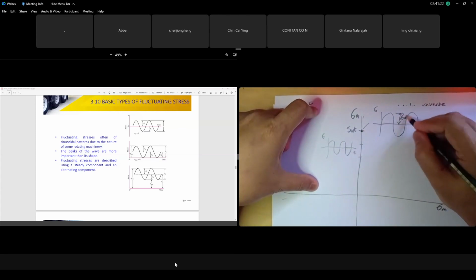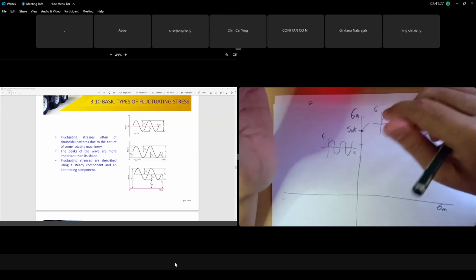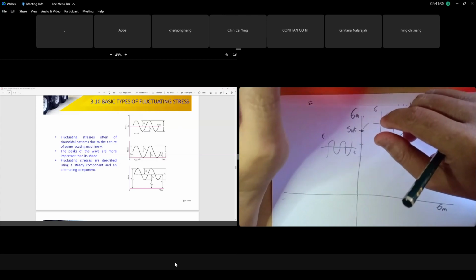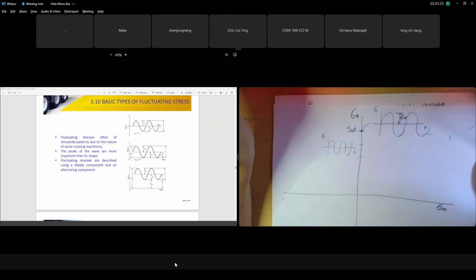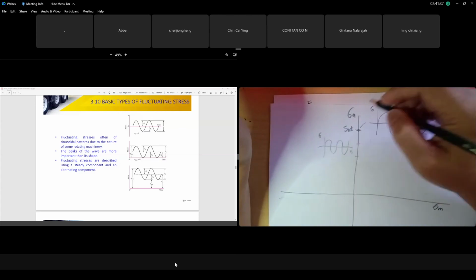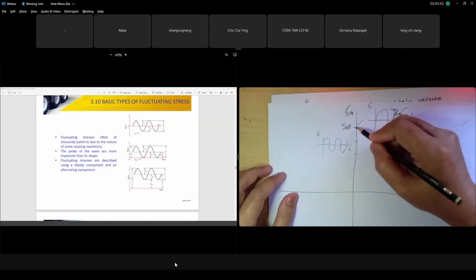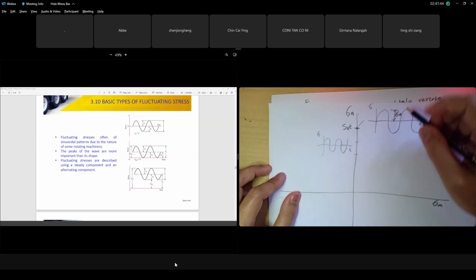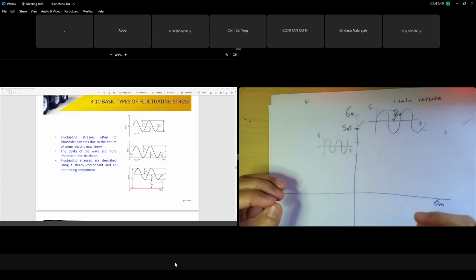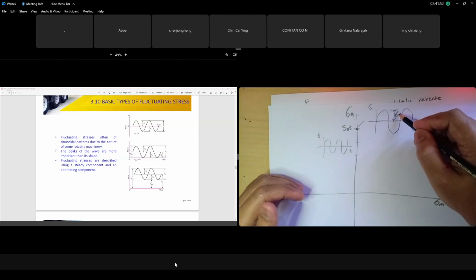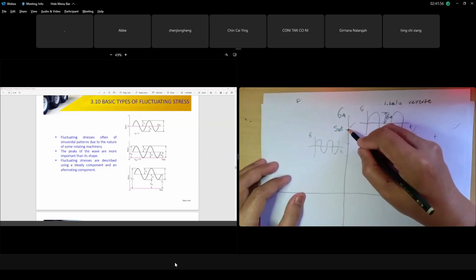In the worst case for a ductile material it is actually yielding, but since the tensile test ends at breaking, the maximum limit is the SUT. If sigma A, the amplitude, reaches that value, the SUT is the border limit. If your analysis shows the load and stress are so high that the amplitude of the completely reversed stress reaches that, it is the SUT.